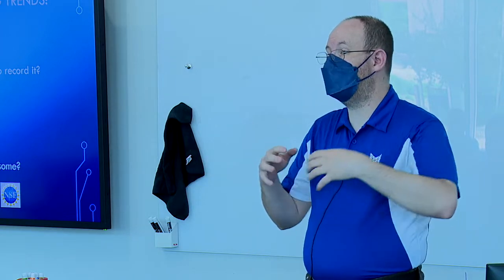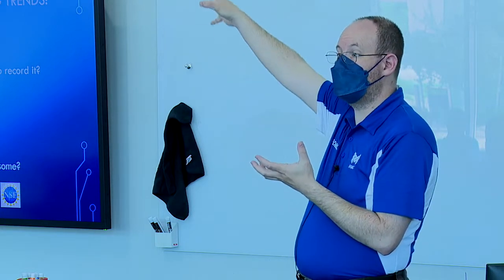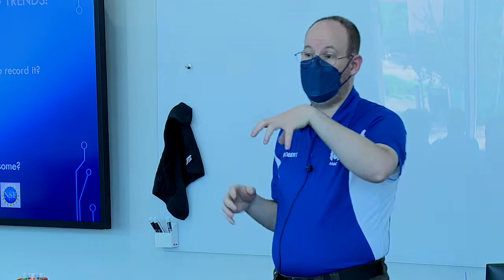Except that we're dealing with technology that's 10 years old. We're also dealing with a processor that's 10 years old, so it may not be able to run all the stuff we need it to operationally and store the data. And we're also going to be pushing that data out through a communication bus. Individually, it may not seem like a lot of traffic, but when you stack up 30 or 40 controllers on a bus, it can be significant.